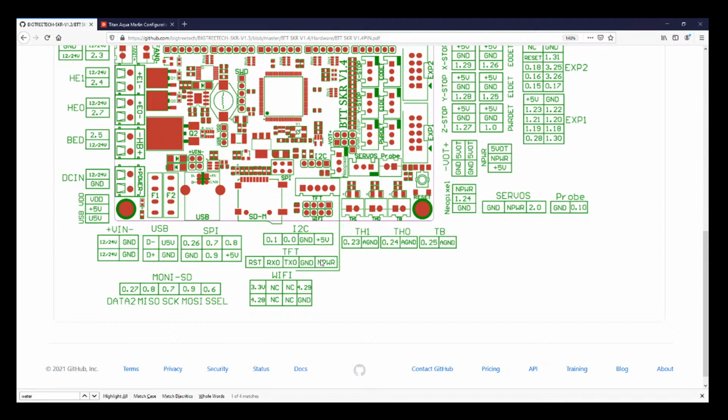So we can test this out by putting the multimeter down to millivolts. And do this very carefully, so we're only measuring the 5-volt chip. So we know that this is ground. Hang on, I gotta unscramble these wires a little. So we're gonna take the probe and put this here for ground. Then we know this is voltage.